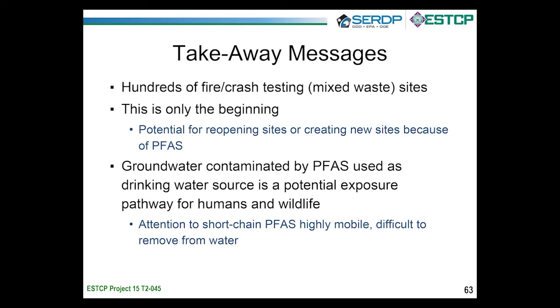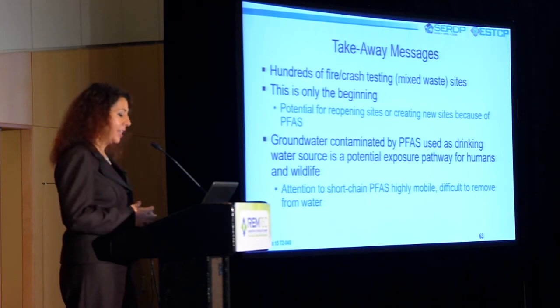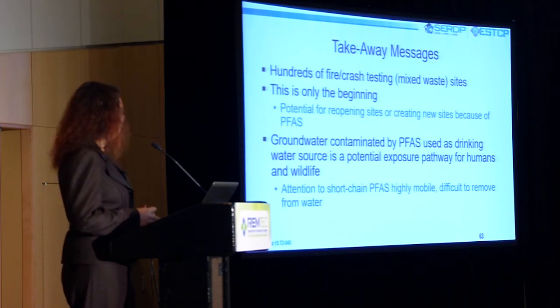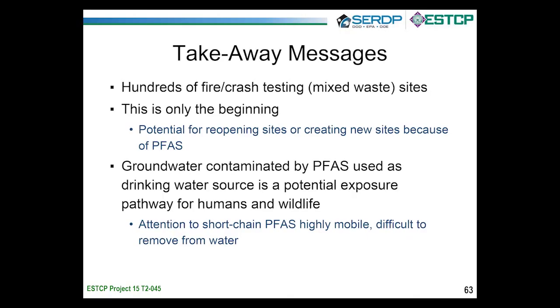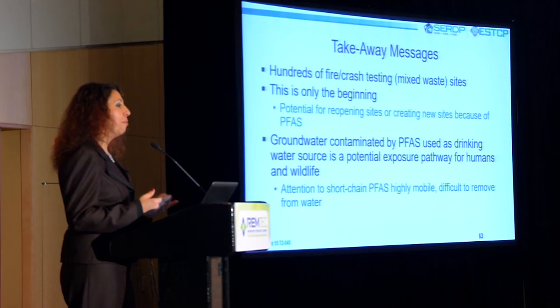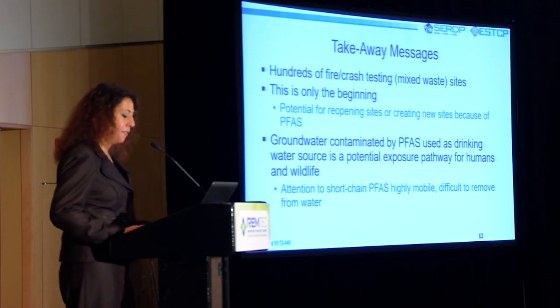Groundwater contaminated by PFAS used as a drinking water source, as you heard from Jason, is a potential exposure pathway for both humans and wildlife. And we're starting to become aware of the potential of the shorter chain PFAS compounds and their mobility in the subsurface and the difficulty of removing them from water using traditional treatment methods like GAC.